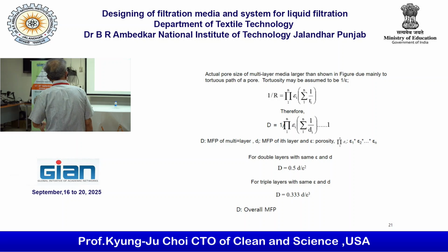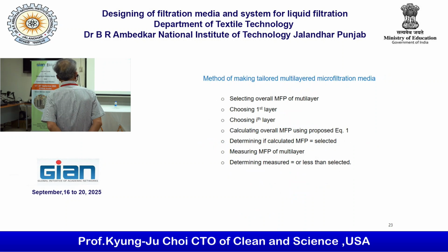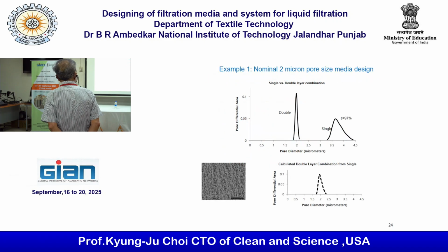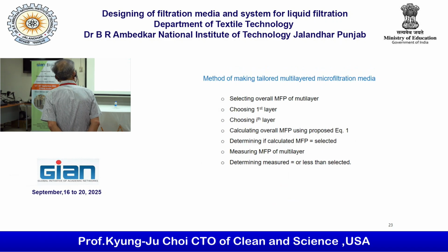So how are you going to make the tailored multilayer microfiltration media? Actually, this is not microfiltration media. The membrane media might be better. So you have to have a target, whether you're going to make 0.1 micron size or 0.001, and then choose the first layer.